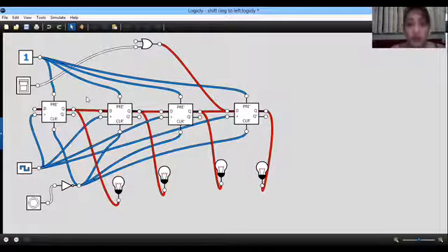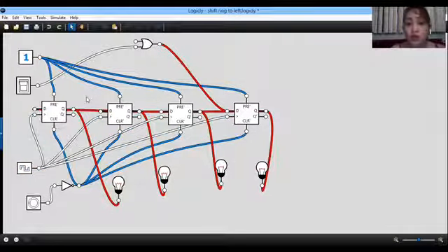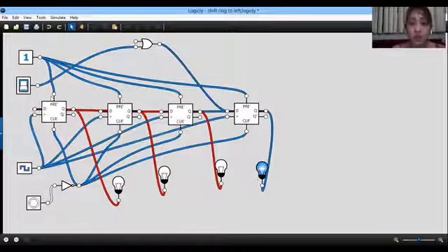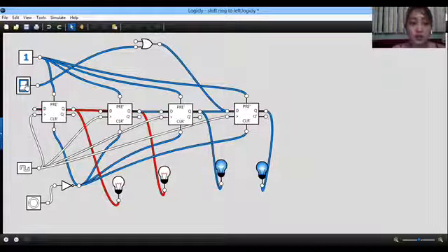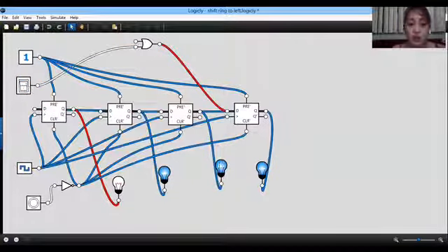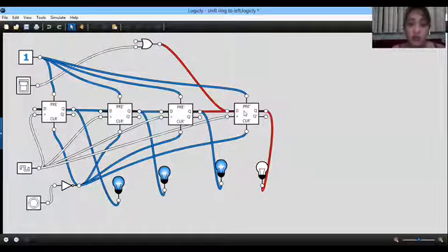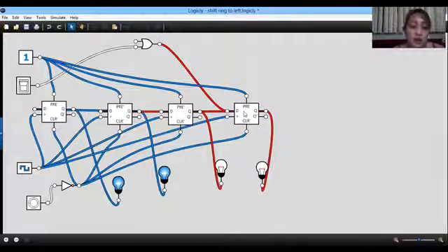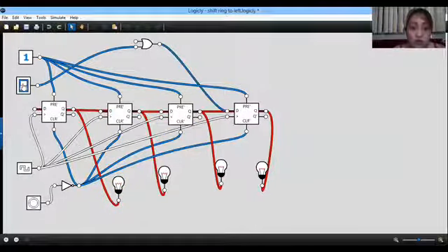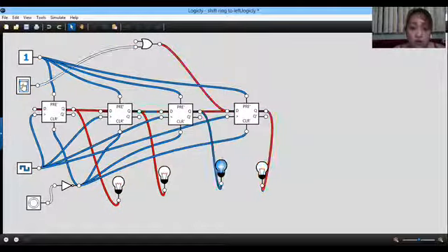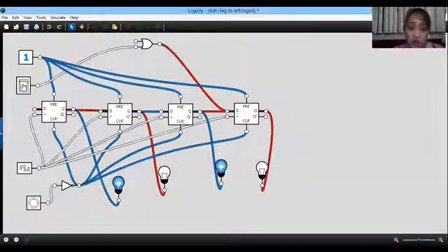Why shift to the left? Again, take note of the timing of the clock. Every time the clock turns on, it gives a signal to the IC. The outputs are synchronized with the clock. On, off, on, off, and the outputs are being shifted to the left.